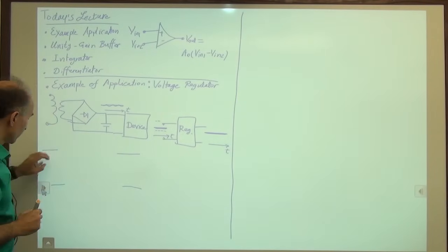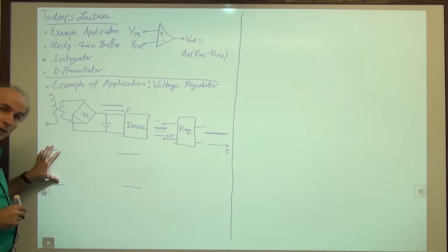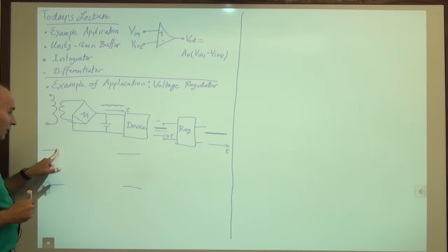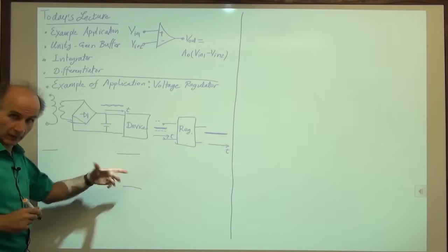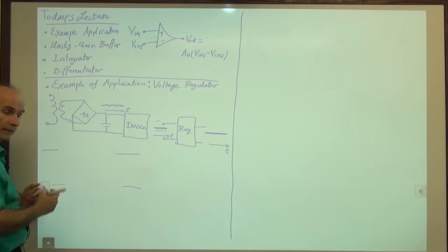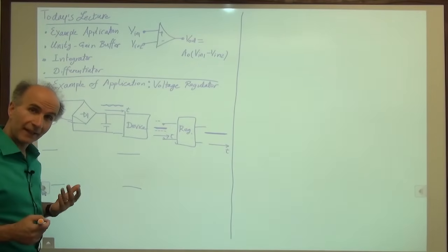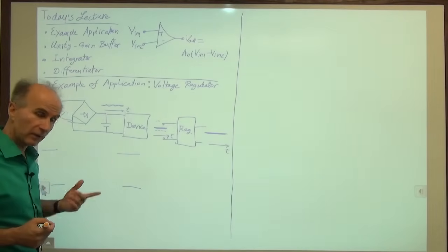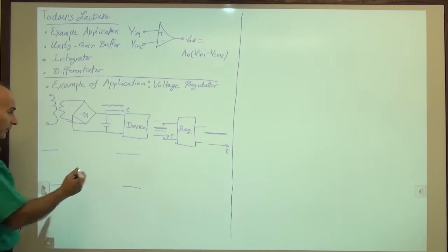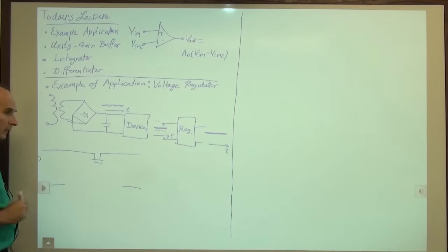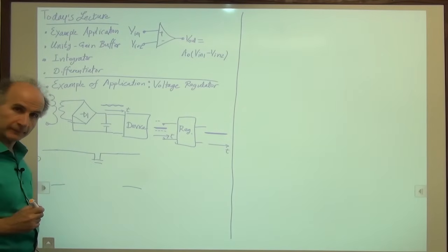Now, if this voltage wants to change, and I don't want this voltage to change, I have to have something between these two to control this voltage, right? Obviously, we need some sort of mechanism. So let's go ahead and use a MOSFET as a variable resistor between here and here. So here's a variable resistor that we connect between these two points.